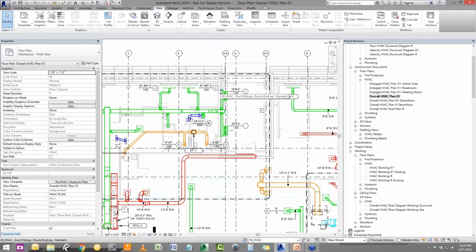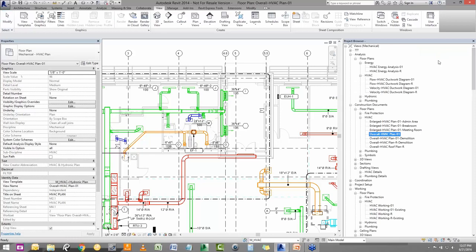We got some questions here on whether or not changing the CFM rate also changes the duct size. The CFM rate does not change the duct size. There are duct sizing capabilities inside of Revit here. You can take advantage of those duct sizing capabilities, which is kind of what we're going to be looking at with the analytics of the color legend. But you can go ahead and enter in some rules for, say, for example, velocity or static pressure, however you'd like to size your ductwork, into the auto-sizing capabilities of Revit, and it will auto-size.